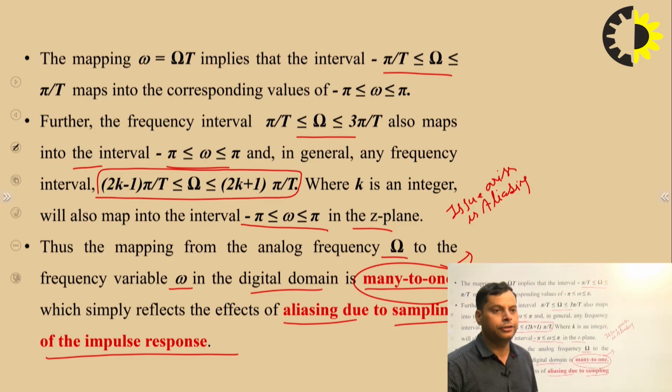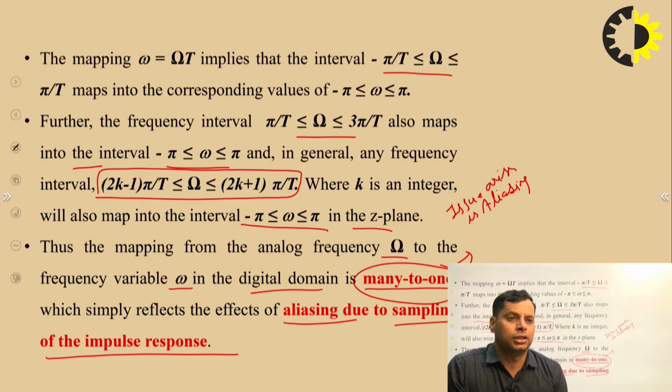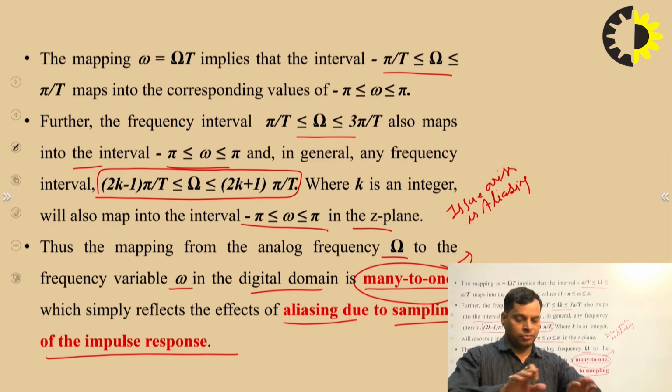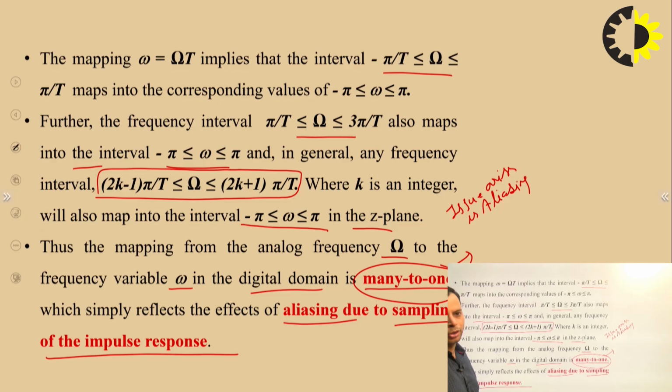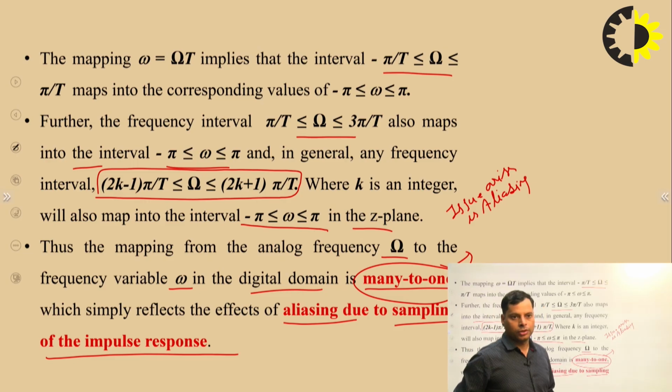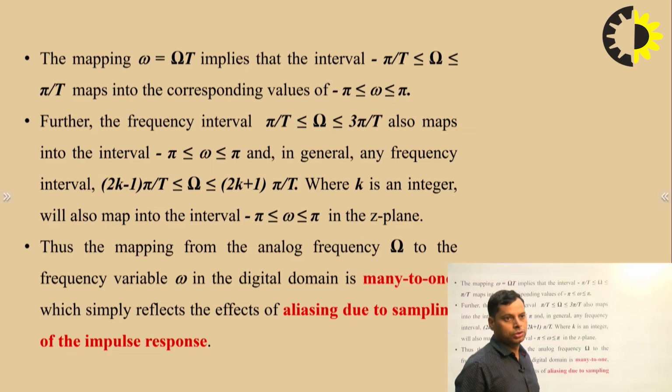Aliasing when introduced, that means what? In general, it is the mixing of signals, which becomes a loss of information, because in the frequency response with aliasing, two frequency bands will be mapped onto each other, and that is the loss of information. So this is not a good sign. The problem that will arise here is the many to one mapping. We can design the filter, but this issue will come out, so focus on the reduction or removal of this issue.